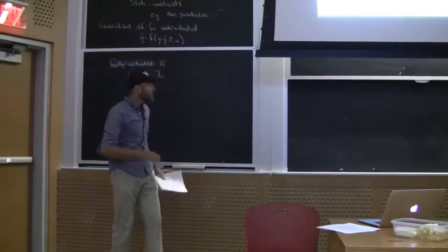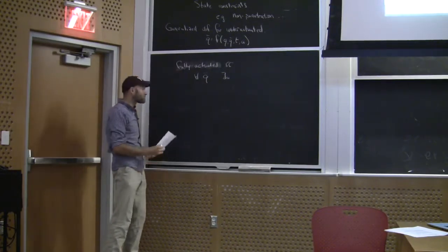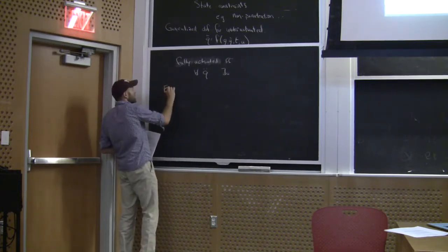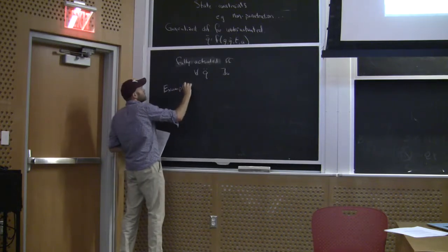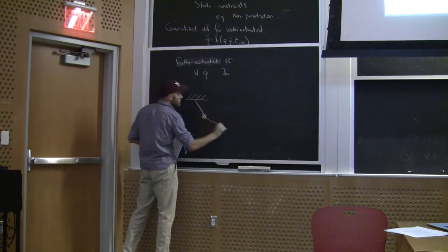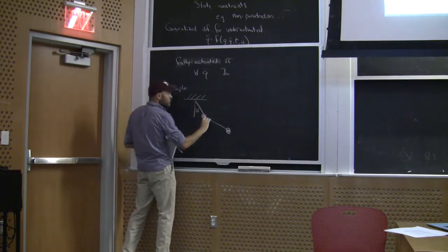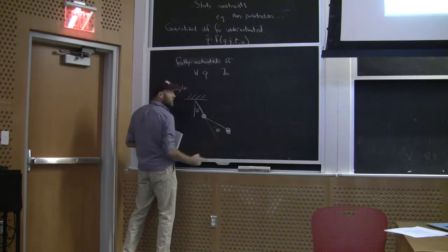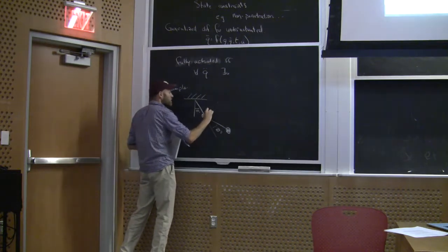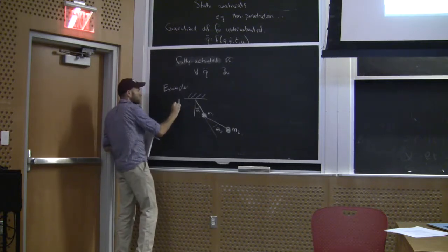Okay, so let's talk a little bit more about robots in particular and how to recognize underactuatedness in a robot. So let's take one of the simplest examples, a simple double pendulum. So here's my simple robot. I can describe its configuration with two variables, theta 1 and theta 2. I'll give it mass, 2 point masses, m1 and m2. I'll have gravity pointing down here.